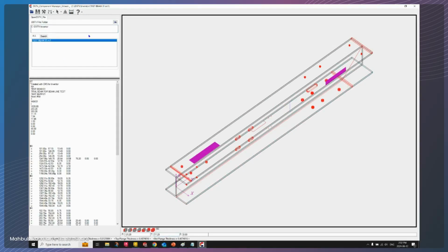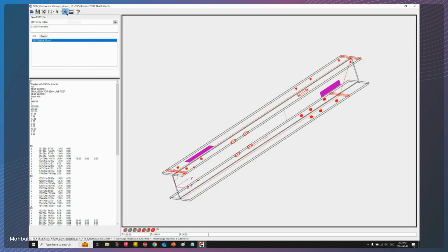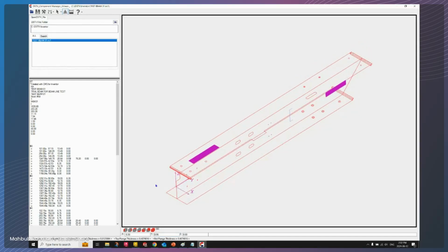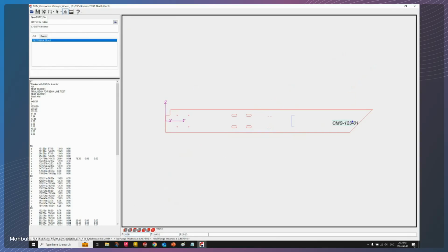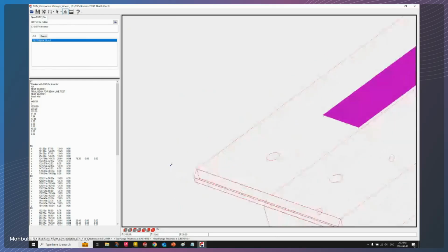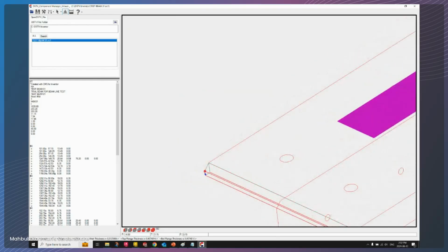Okay, so as you see, that's my 3D view. All right, and if I just turn off my shape lines, it's going to show my CNC lines here. So all those red lines are CNC lines. If I just go to the front view here, as you see, that's coming from the embossing feature. That's my marking content, the KO. That's my pop marks that we had, right? And that's the fillet. We had the cope there, right? And that's the bevel, right? We had a tiny bevel there. And the bevel descriptions are also added here as well, which is part of the AK on the top flange.